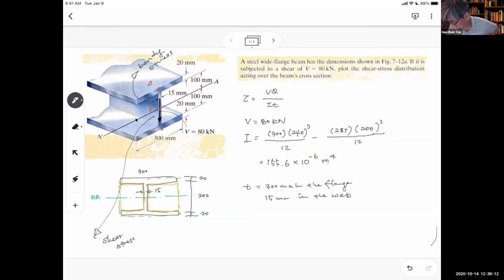So you can see that this I-beam is very well designed, effectively carrying both bending stress and shear stress. This is a very clever design to carry both bending and shear. Bending is carried by the flange, shear is carried by the web. Very cleverly done. That's why you see a lot of I-beams as a structural member for the beam.